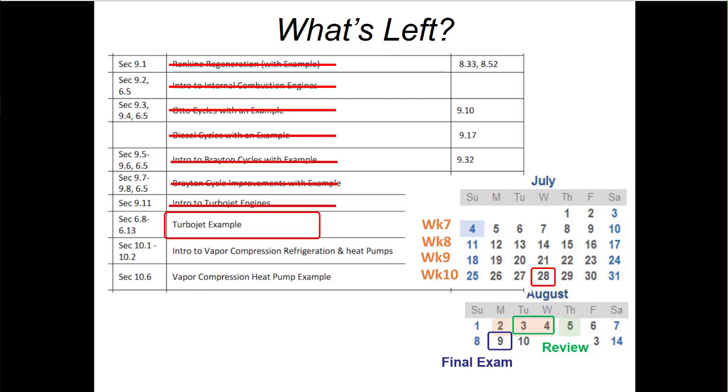The good news is that it's not review, but it's kind of like a 4-component Rankine cycle, but we run it backwards because its job is the opposite, right? So heat engines, we're putting heat in and getting work out. These temperature control devices like refrigerators and heat pumps, we're putting work in and we're controlling the direction the heat is flowing. So it's kind of like running it in reverse. And then we'll do an example with that.